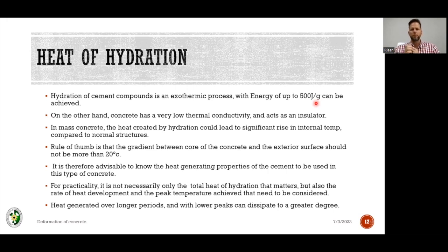And the reason it's doing this is we put this calcium carbonate and extenders and correctors into the kiln, and we burned it for almost 30 to 40 minutes in a kiln at 1,450 odd plus degrees centigrade. It's now getting back at us. This is it getting back at us. It exudes this heat. It's taking back that energy and it's exuding it. And that temperature builds up in your concrete. We know that concrete has very low thermal conductivity, so it actually acts as an insulator. Some time to heat up, but it can hold that heat.